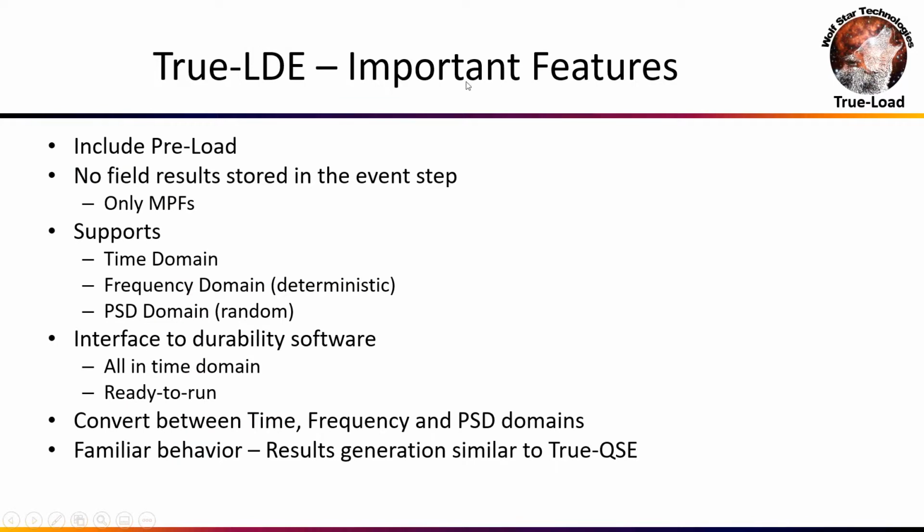So the great features with LDE: you get to include preload. There are no field results stored on the event set, only the modal participation factors. We support time domain, frequency domain, and PSD domain. You have an interface to the durability software, all in the time domain. So even if you're doing a frequency or PSD domain solve, when we push your results off to a durability software, we're going to push it into the time domain, so it's actually the correct solution.